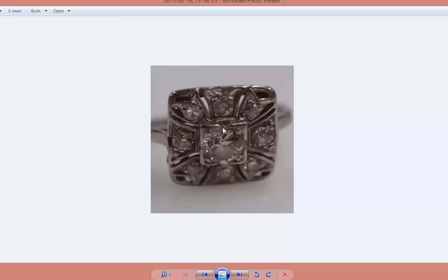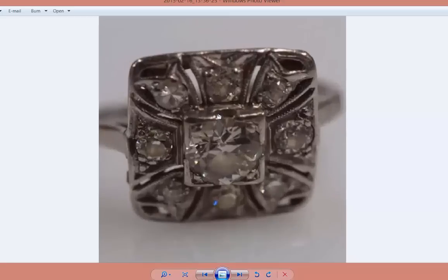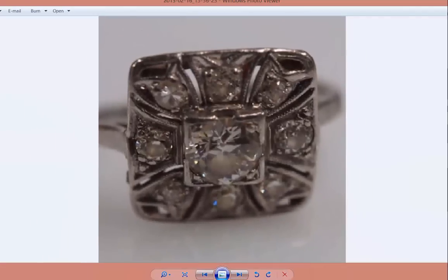So let's go back and show you this again. If you zoom in here, you'll see that this has a groove in there. There's a groove down there, and there's a groove in there, and that breaks this up into what appears to be sort of like what would have been a princess cut actually. But you can see there's a prong here, and those are the prongs that we've drawn. So we've got these 4 prongs actually holding the stone up, but this gives the illusion of it being square. So we need to break up the solid wall by introducing these 4 U's that we have there.